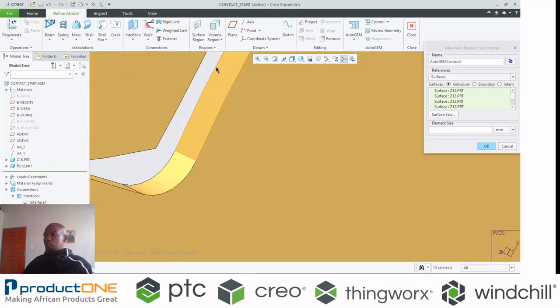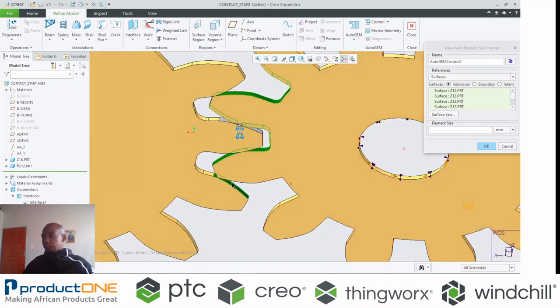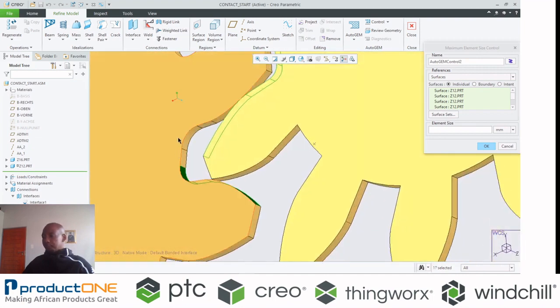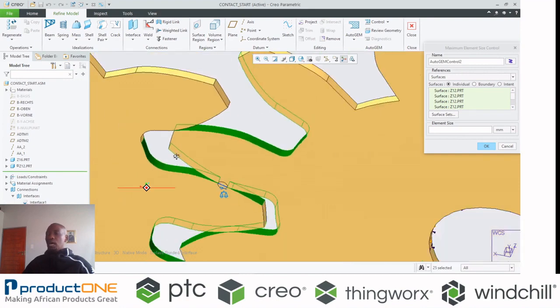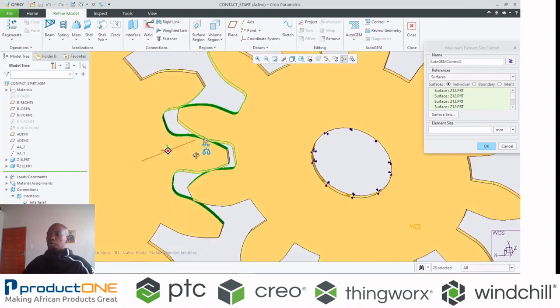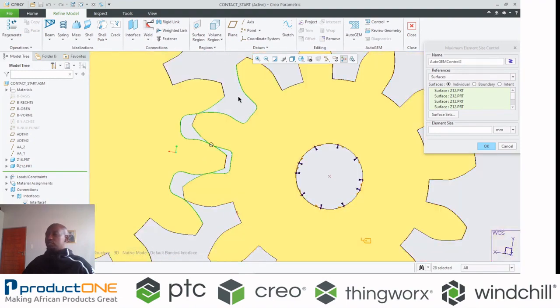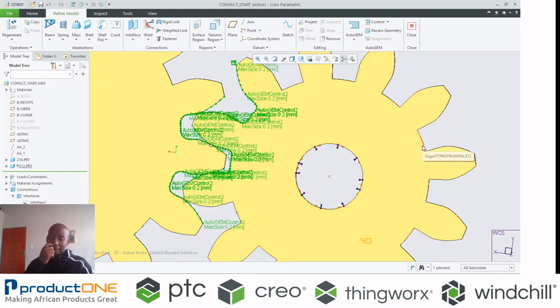So we're talking about all these other areas. We'll come back just now onto the volume regions, so I'm not going to define them now. So I'm specifying where I've got what we call radiuses and high stresses, in this instance. And please bear in mind, I've removed rounds and fillets in other areas where they are not going to have any impact to the results, if you can see there. So essentially, let's make it 0.2. All right, so that's the size of my element.